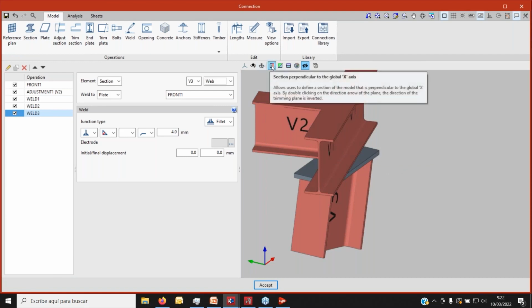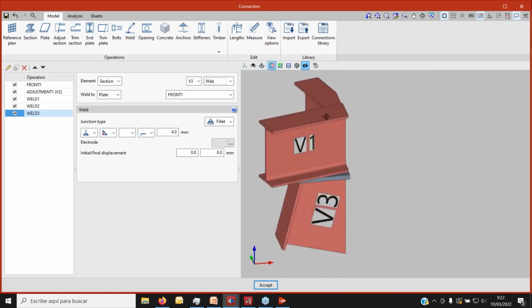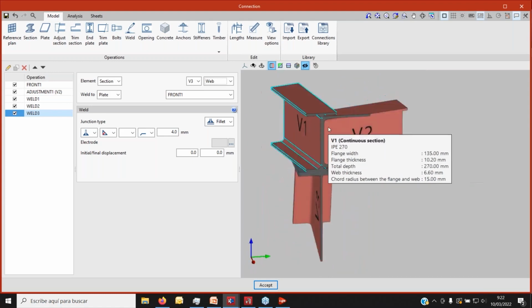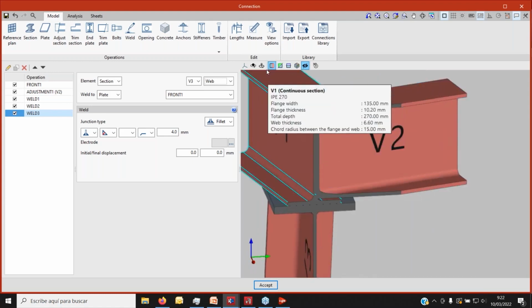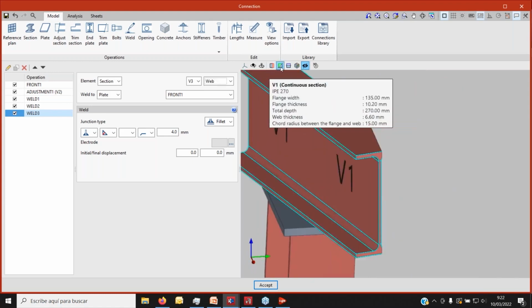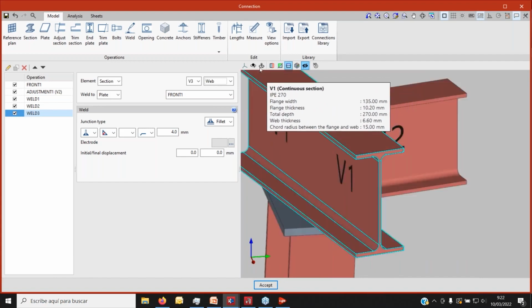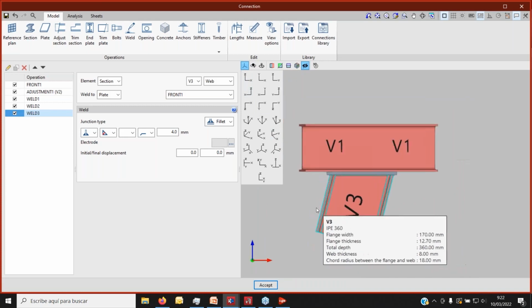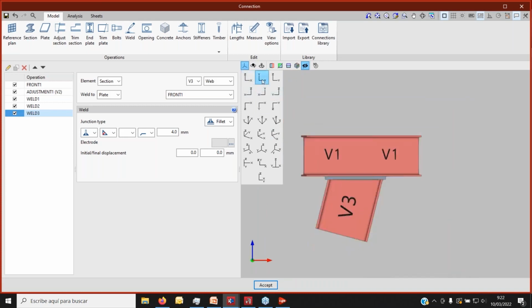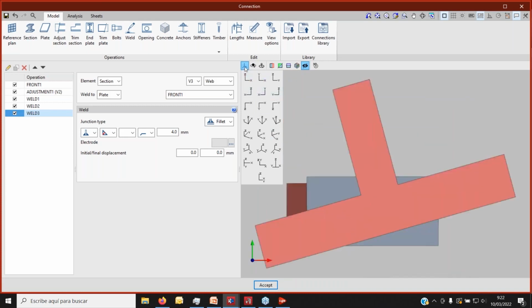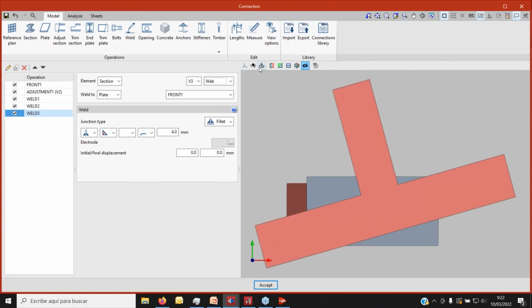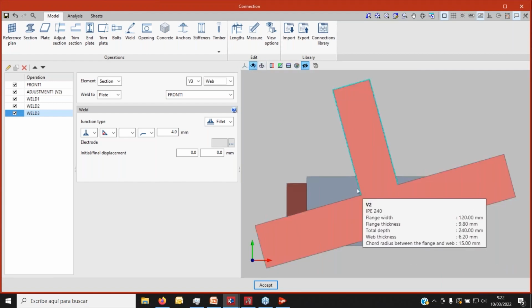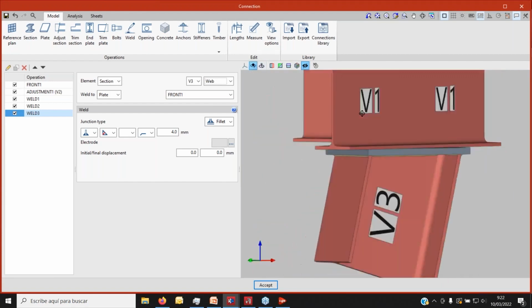We can also create sections like this one in case we would like to take a look at how different pieces are matching internally, both vertically and horizontally, like so. We can force a projection as well in case we would like to work only with elevations, plan views, and so on. And we can freely orbit around the point, as you can see here in the 3D view.